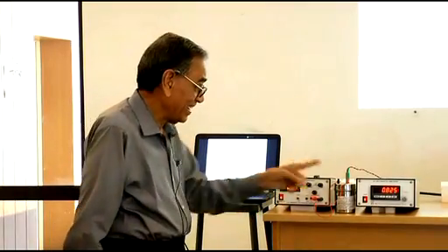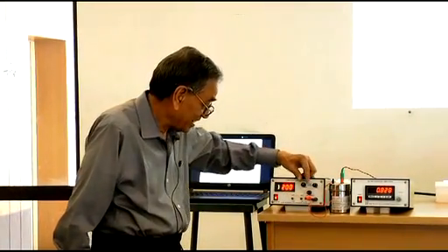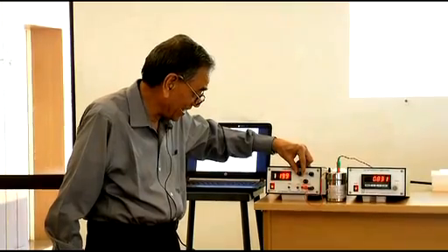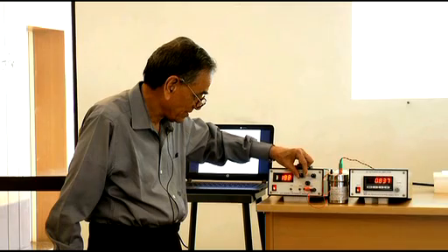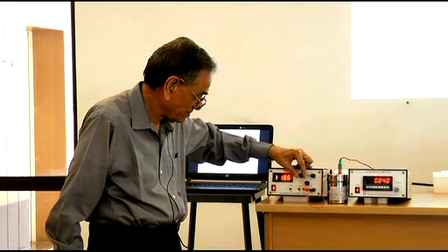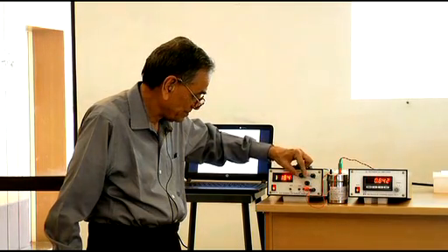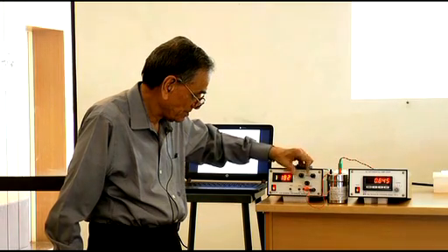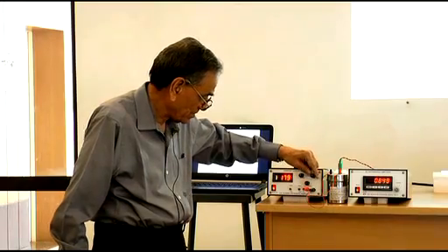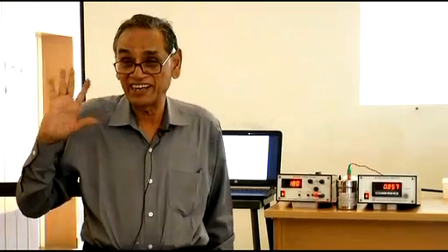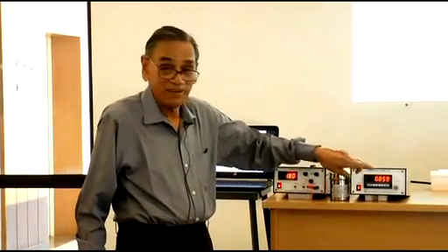After noting the current and the reading of the thermo EMF, reduce the current to 180 milliamperes. Okay, 180 milliampere. Now the reading will start coming down. You have to wait for 45 minutes. First reading 1 hour, subsequent readings 45 minutes, till this becomes steady.